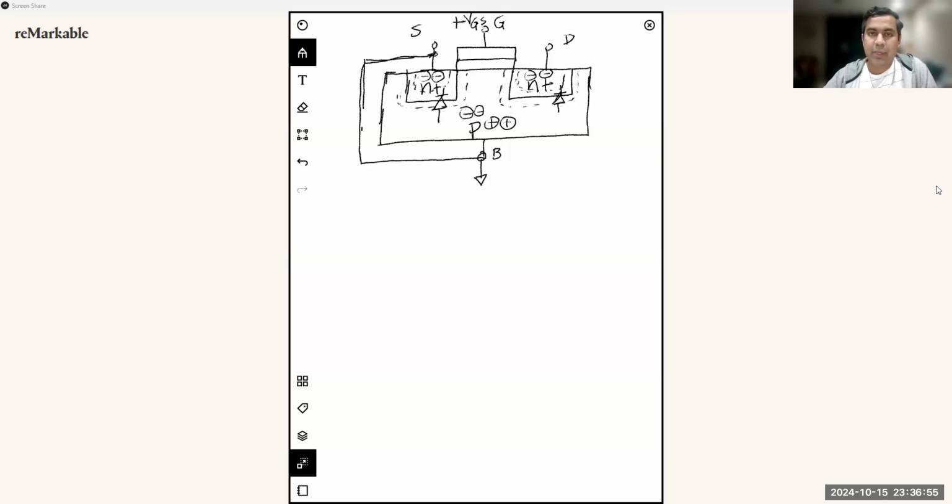So whatever voltage you apply at the gate terminal is the VGS voltage, where the source voltage is at 0. Now if you apply a positive voltage at the gate terminal, that will create an accumulation of positive charges inside the polysilicon layer of the gate. And this polysilicon layer is insulated from the silicon substrate down below by the silicon dioxide gate oxide layer.